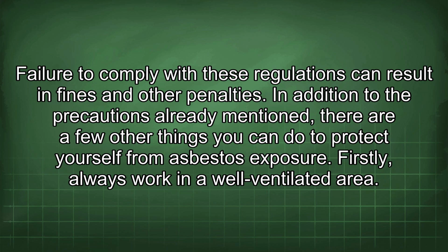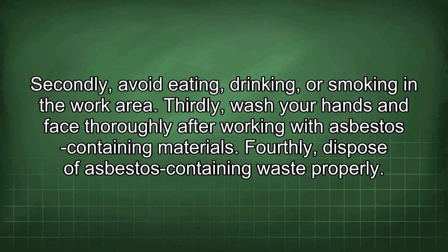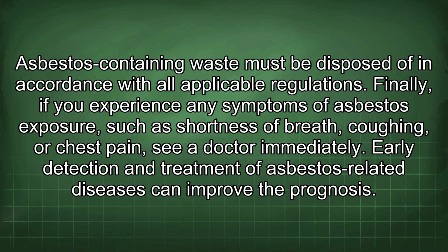In addition to the precautions already mentioned, there are a few other things you can do to protect yourself from asbestos exposure. Firstly, always work in a well-ventilated area. Secondly, avoid eating, drinking, or smoking in the work area. Thirdly, wash your hands and face thoroughly after working with asbestos-containing materials. Fourthly, dispose of asbestos-containing waste properly.